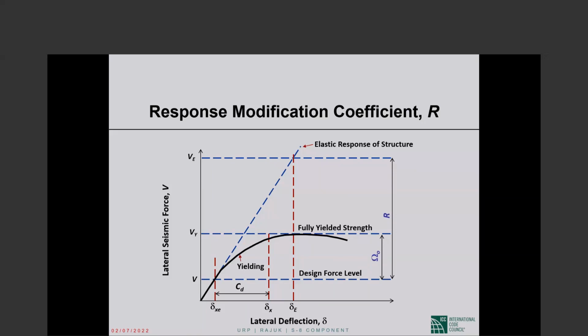Let us say the analysis that produced delta sub xe, the elastic analysis of the structure under code prescribed seismic forces, gives us a bending moment of 100 foot kips at the support section of a beam. So at the support section of one beam, we calculate a bending moment of 100 foot kips negative under the design earthquake forces.